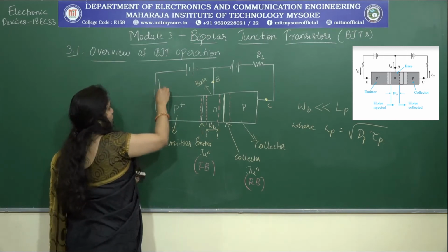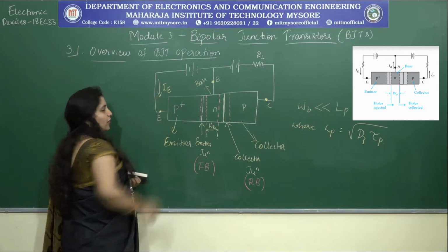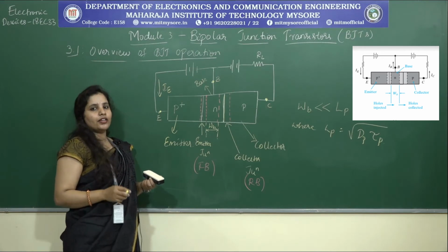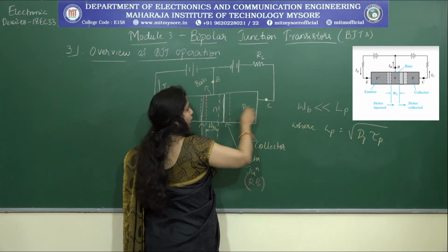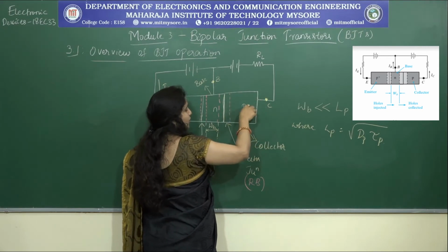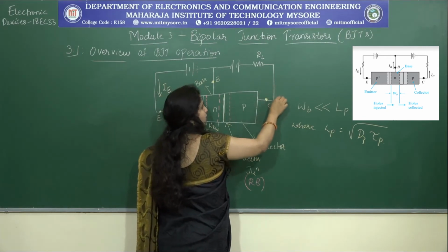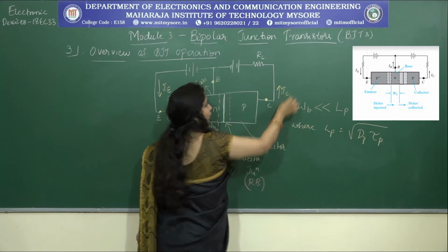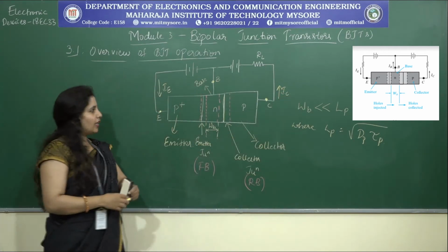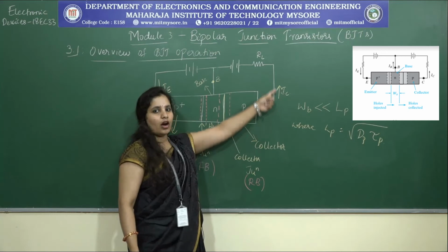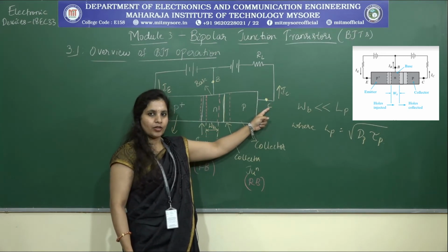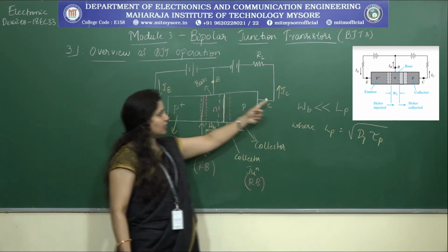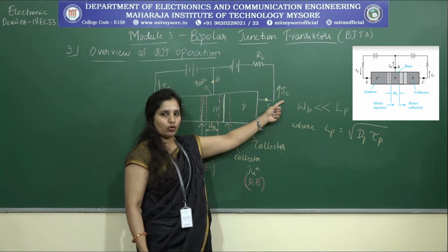Therefore, whatever the current, I'll be representing as the emitter current, and whatever holes we have, it has to somehow get injected and then come out like this, right? Therefore, it is coming out of the collector region. As a result, I represent the arrow direction to be outward at the collector region. So this is the incoming current and IC is the outgoing current.